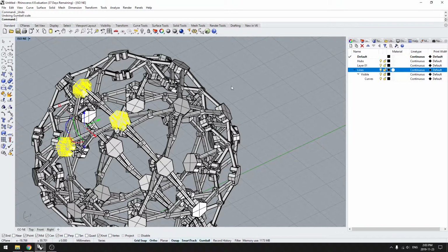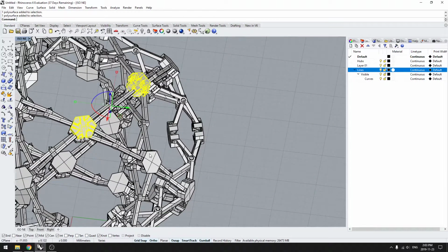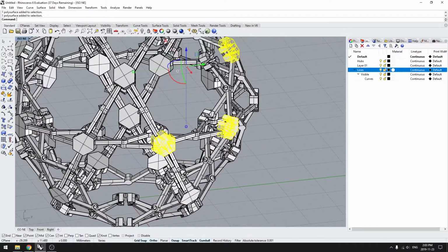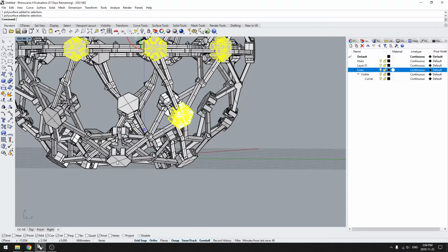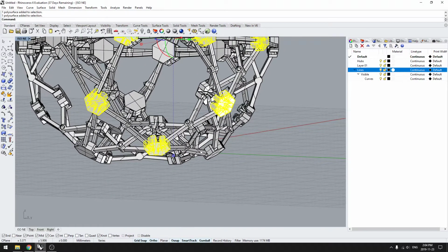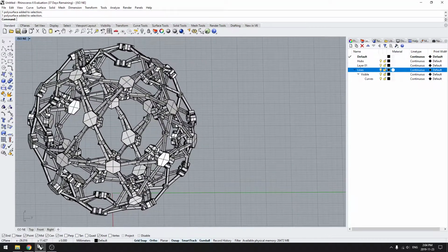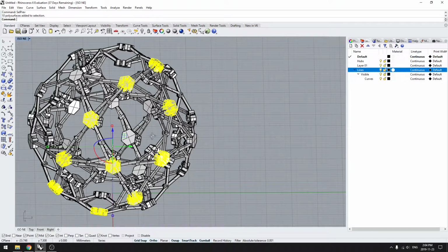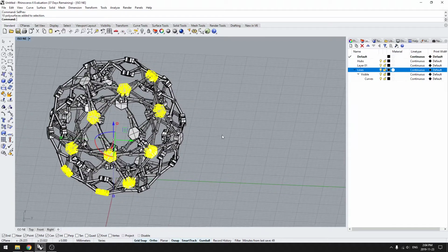So these are really useful because let's say you're trying to select a bunch of objects and you're like, maybe I want to get all the hubs in this entire sphere, right? And that's gonna take a long time. And halfway through, maybe I make an oopsie, I click somewhere else, and my selection is canceled. So how do I get that back? I'll just do select previous, and it gives me my previous selection back. So instead of going and selecting everything again, I can just select previous.